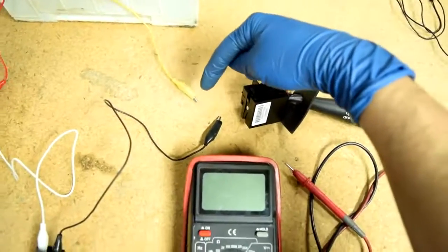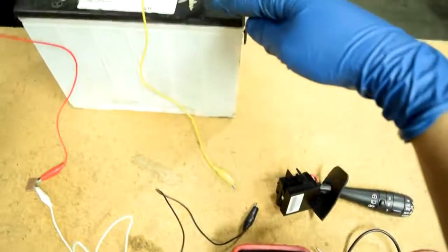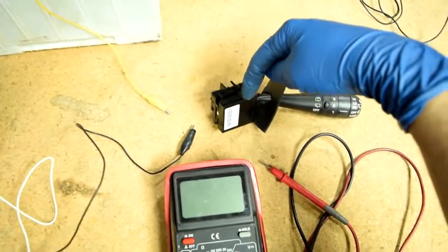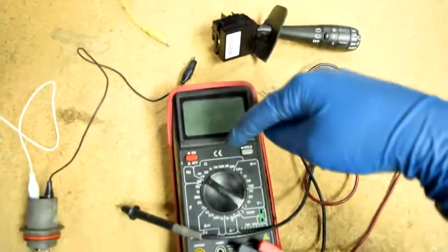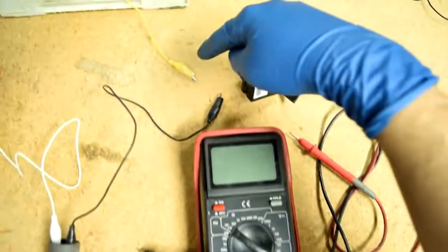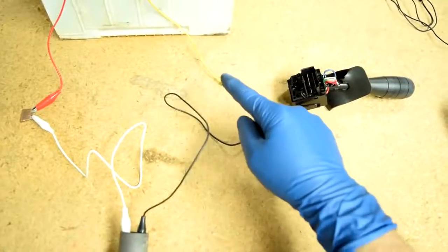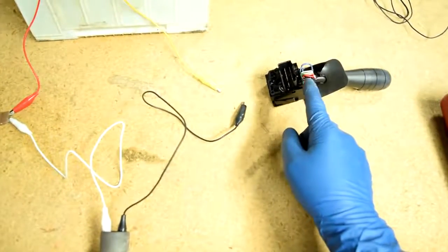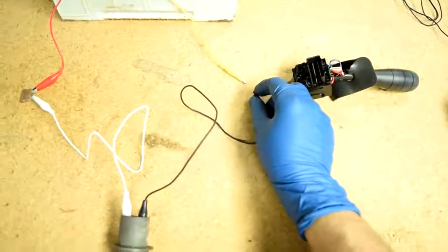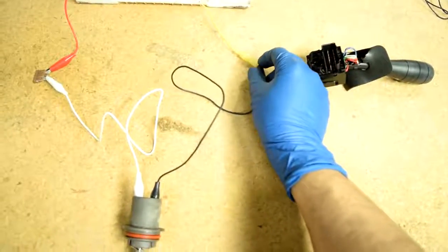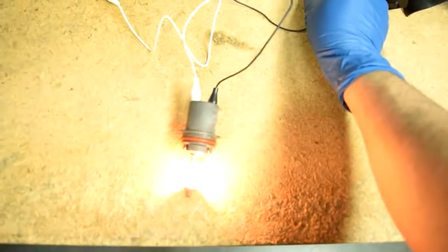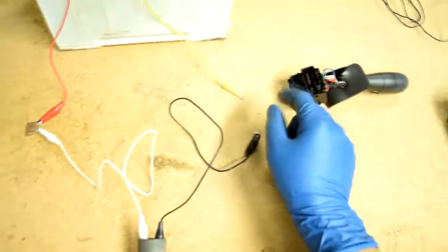And then in order to make sure you have ground at the wire that's supposed to supply ground from your battery to your switch, all you have to do is to check for continuity using your multimeter from this wire to any ground. And of course, if everything checks out, you probably have a bad switch. And if you want to make sure that's your case, all you have to do is to jump these two wires. And if your headlights come on, then obviously the issue is with your switch.